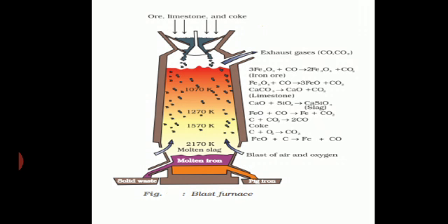But wrought iron is of limited applications, because it gets rusted very easily, so hence it is converted into steel. We can convert it into steel by the Bessemer process, by the open hearth process, and by the LD process. LD process is the most economical process because it involves less expenditure and is more productive. The operating cost is also low in the LD process. LD comes from Linz and Donawitz.